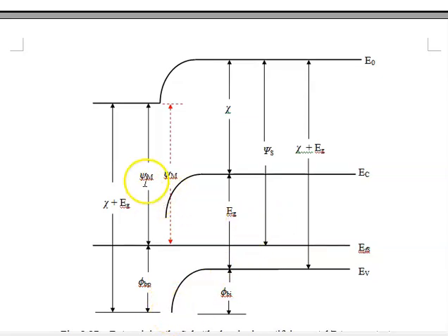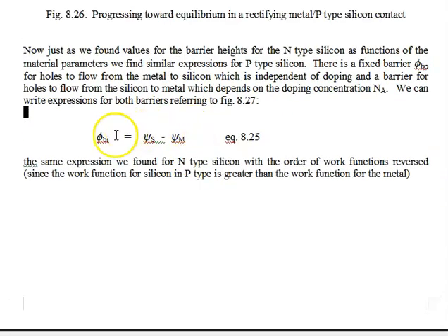So just from the figure, we take the metal work function and scoot it over here, and we know that the silicon work function is greater than the metal work function. If we take their difference, phi sub s minus phi sub m, we get this distance right here. Just move that over. Phi sub s minus phi sub m is equal to phi sub bi. Well, that should look familiar. The amount of band bending is equal to the difference in the work functions.